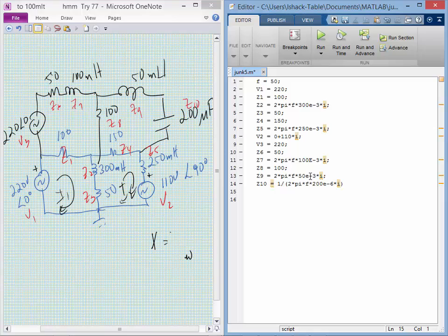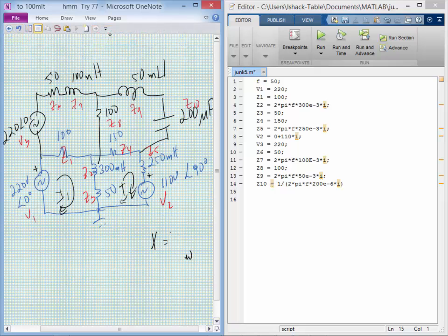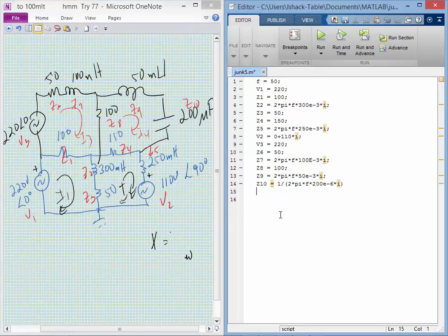So loop 1 and loop 2 stay. My loops all change now. So as we look at my loops right here, there's our third loop, I3. Here's my fourth loop, I4. So we're just going to go ahead and start sticking our loops, do our Z matrix. Z is equal to, loop 1 is going to be the same.